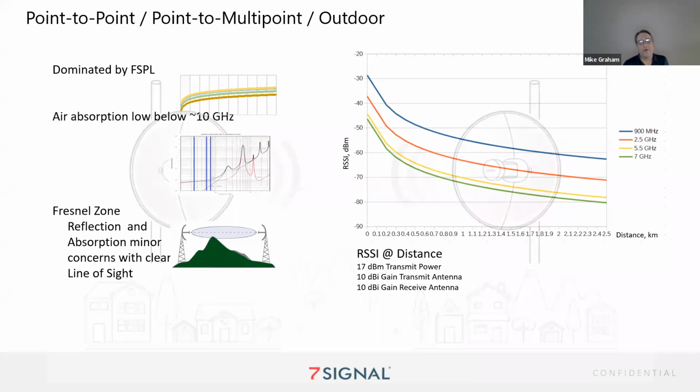I had an engineer that worked for me, and he had the visual sight test and the truck test for links. And for short links, it kind of works. If you have visual line of sight and there is enough room to drive a big truck right down the middle of the beam, you're okay. And if not, you need to do the math. Yeah, so that's a good rule of thumb. Worked pretty well.